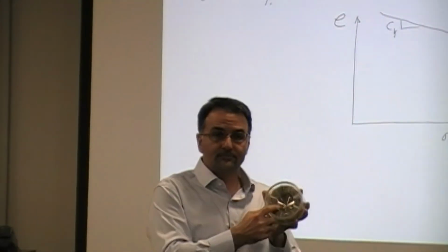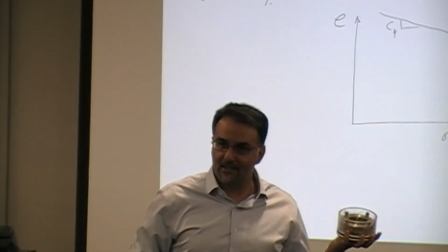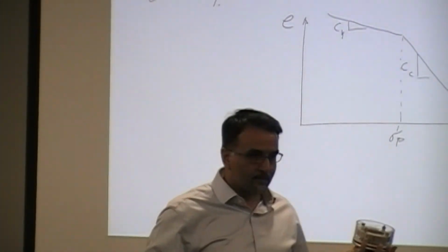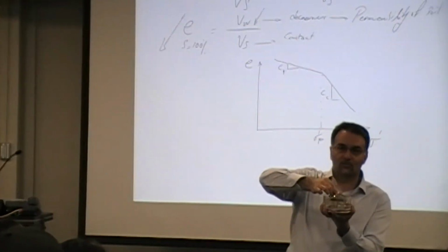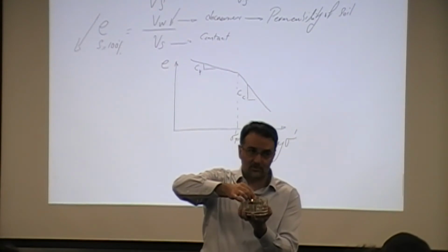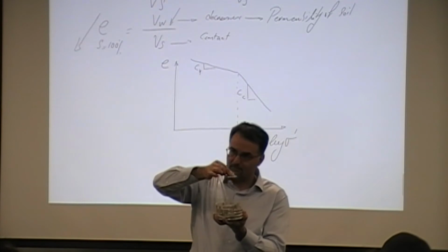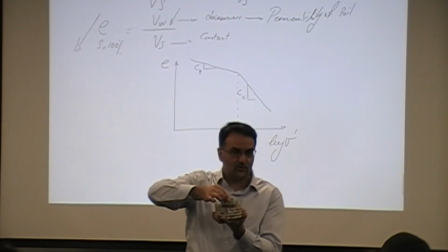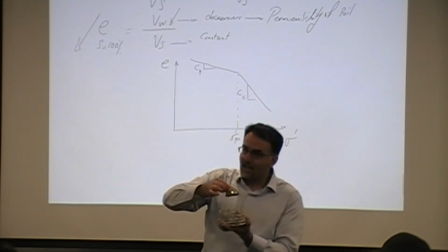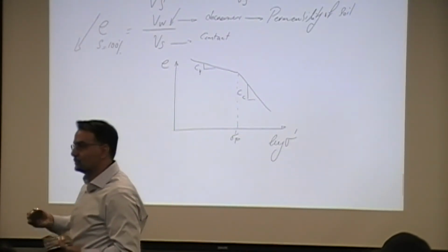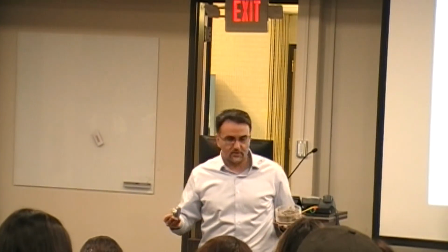And you fill this one with water, right? So it's going to be full of water, meaning that the soil is fully saturated. Right? And you place the porous stone and the loading plate at the top of the soil right here. And this would be the mechanism that you apply the load. Right? You use different surcharges, different magnitudes of weights at the top of that to be able to control the magnitude of the stresses. Right? And you do it at multiple increments. Typically it's 10 points or 7 points.